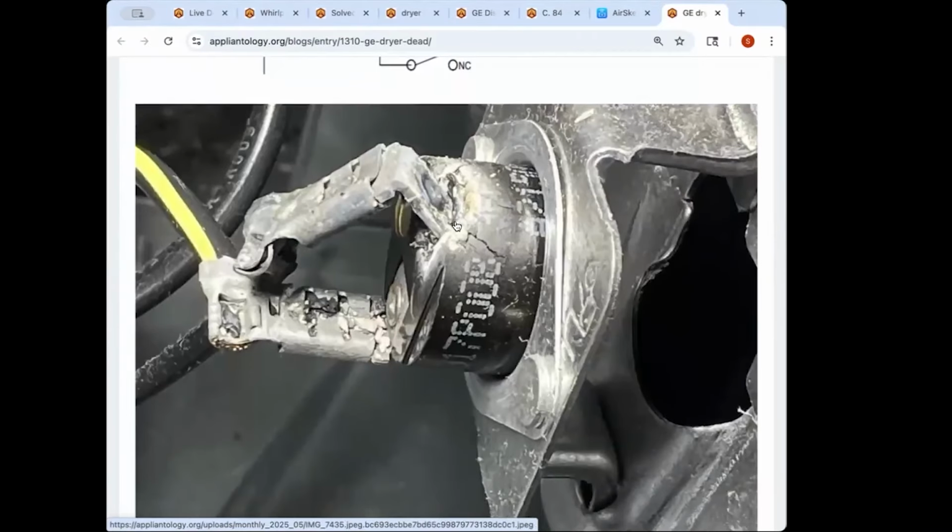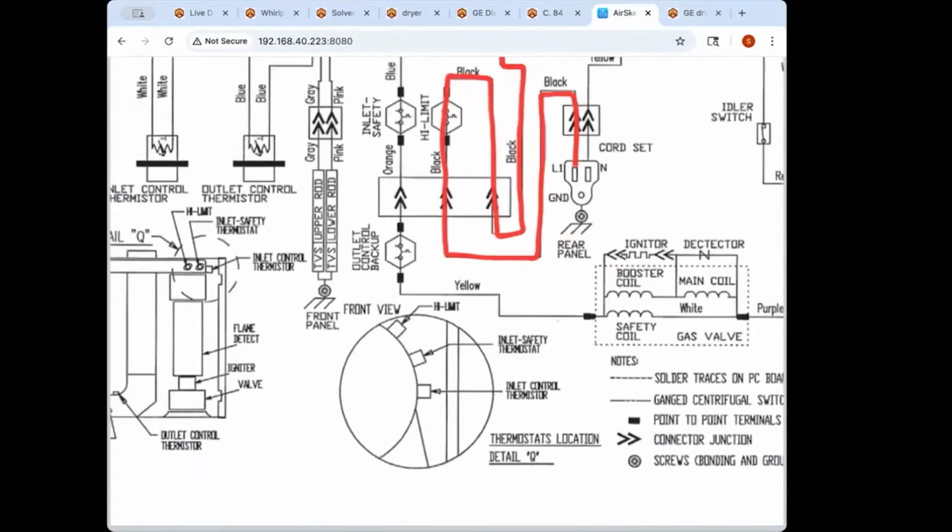But it does look like the wires are touching though. I don't know, it could have been. I don't know on that. That was just posing for the camera. So does this fuse react to temperature or current? High limits are temperature controlled switches. Yeah, this is temp. In fact, go to the schematic, Sam, and they tell you that explicitly by the symbol.